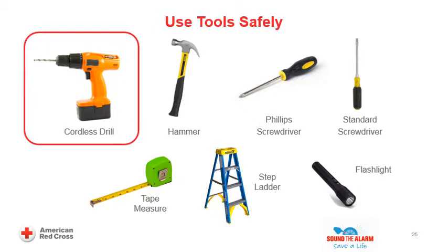Insert the bit into the drill chuck and tighten by hand or with a chuck key if applicable. If using a chuck key, remove it from the drill chuck before starting the drill. Keep your hands and fingers away from the rotating drill chuck and bit. Do not apply excessive force while drilling. Use caution when changing drill bits, as they are sharp and can become hot during use. Only use the battery and battery charger provided by the manufacturer. Never stop the rotation of the drill chuck or bit with your hands or fingers. Always clean your work area upon completion of the drilling task.